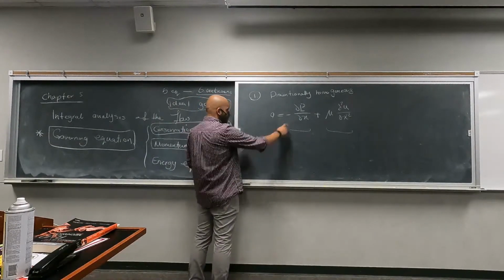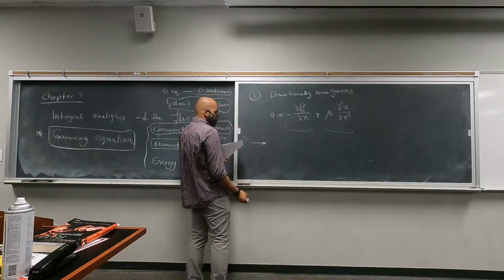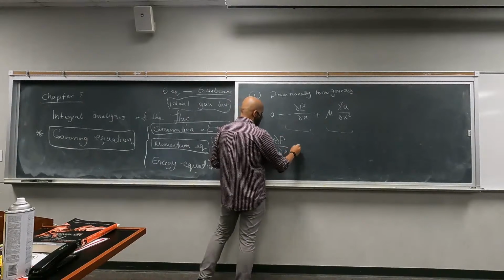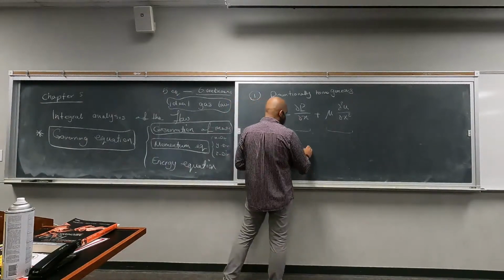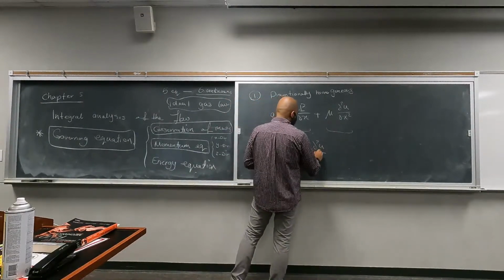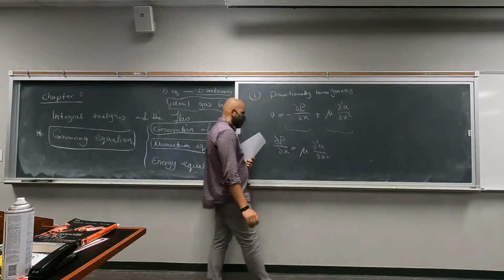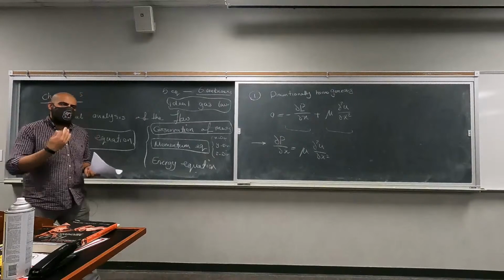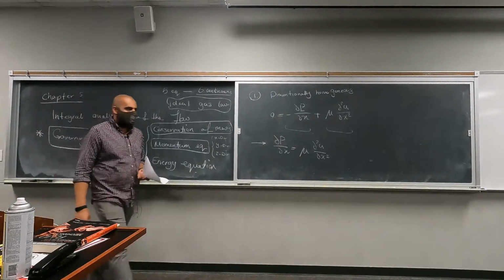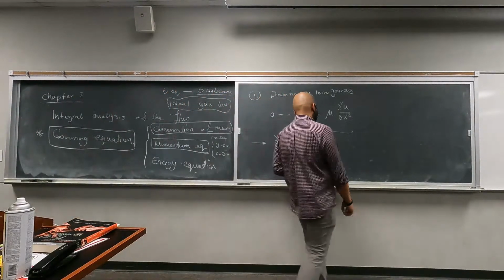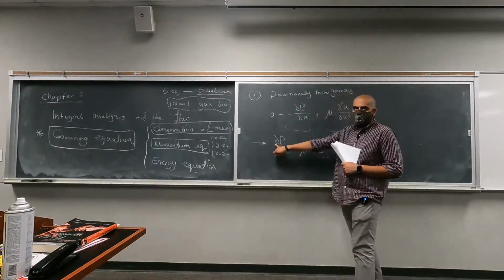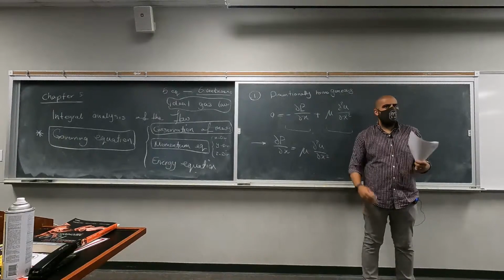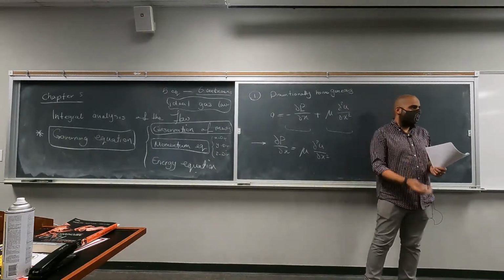So we're going to move this term over to the left-hand side. Partial p partial x is going to be equal to mu partial squared u partial x squared. So let's see what is the dimension of the left-hand side, and then what is the dimension of the right-hand side. The partial operator itself doesn't have any dimensions, right? This is something hopefully we knew from basic physics or mathematics.